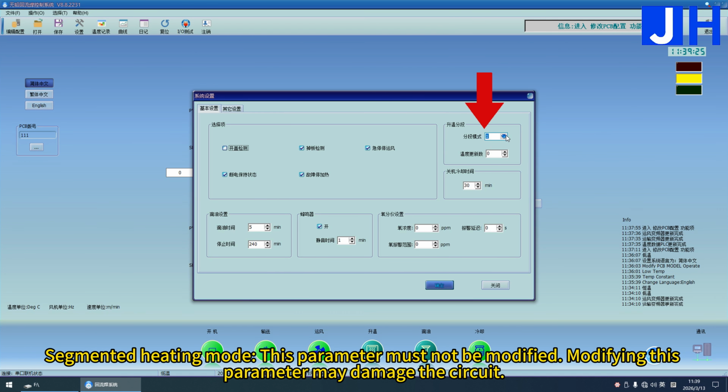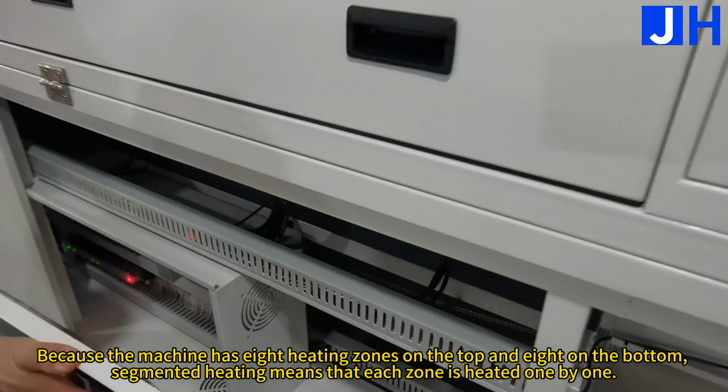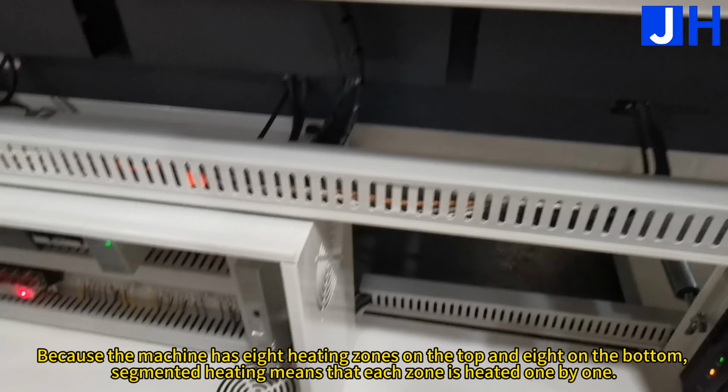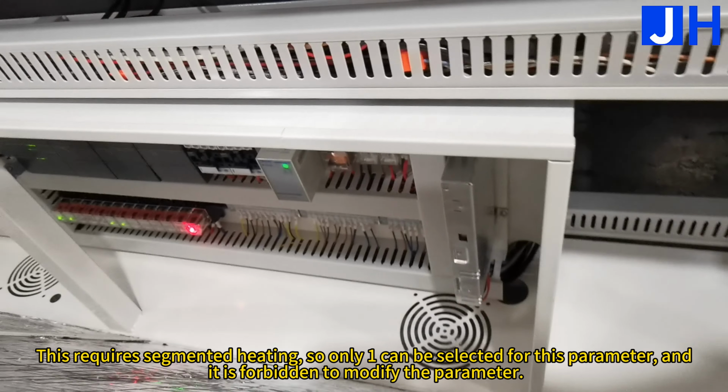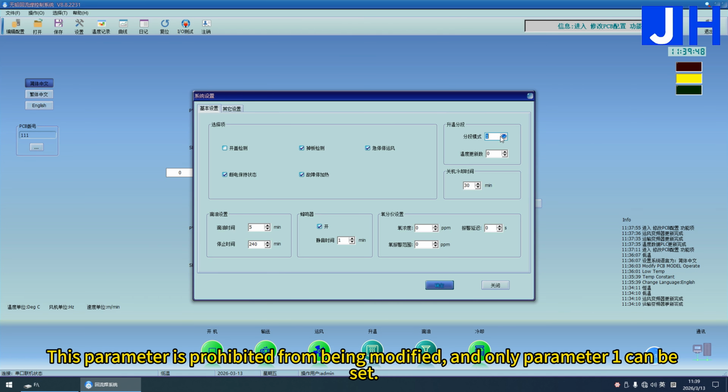Segmented heating mode. This parameter must not be modified. Modifying this parameter may damage the circuit. Because the machine has 8 heating zones on the top and 8 on the bottom, segmented heating means that each zone is heated one by one. This requires segmented heating, so only one can be selected for this parameter, and it is forbidden to modify it. Only parameter 1 can be set.